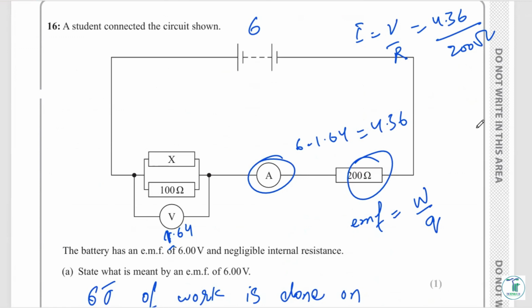If we have the total voltage, whatever it is, and if we have the total current, we'll get to know the total resistance as well. Everybody knows that the current in series is constant. If we have 21 milliampere over here, that would be the same current passing through this part as well. So I'm going to calculate the total resistance of this part first of all, right?